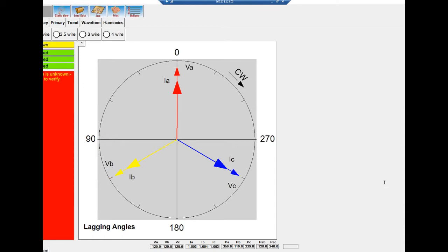With that, right below all of the controls I was talking about, you get the ability to choose between what section of power quality you want to look at. Wiring check is this screen here, and it gives you the ability to choose service wires. Service wires being how many wires are at that site, or how many are applicable to the site or service that you are hooked up to. For example, with this being a Y service I'm generating here, I could select 4 wire.